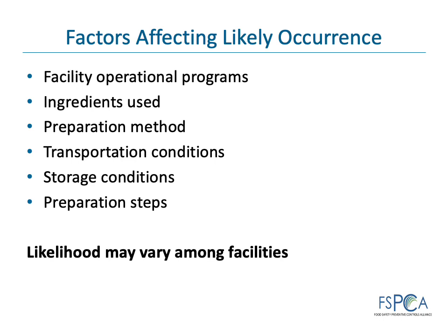Another example may be a facility that does not pack in glass containers, prohibits glass in the facility, including instrument gauges with glass faces and watches, even for visitors, in the production area, and uses shields on light fixtures to prevent breakage. They may determine that glass does not require a preventive control. Conversely, a facility that does not have the resources to manage such a program or that packs in glass may conclude that the hazard presented by glass requires implementation of preventive controls.